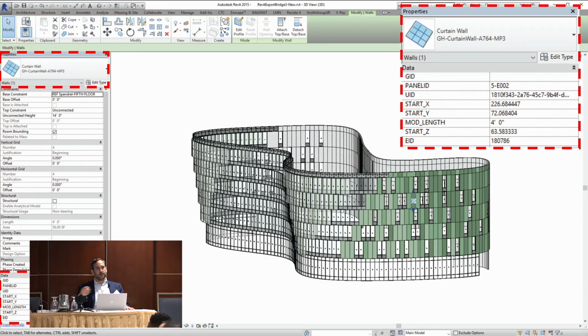So we've got this great Revit model that was built as part of this project. We've got fantastic data built into it, X, Y, and Z coordinates. That's how we communicated with Skanska, things like edge of slab and panel coordinates. We've got, most importantly, the panel type. What is it, glass? What kind of glass? What type of metal panel? All that fun stuff. So we thought, how can we overlay these two on top of each other to make this work?